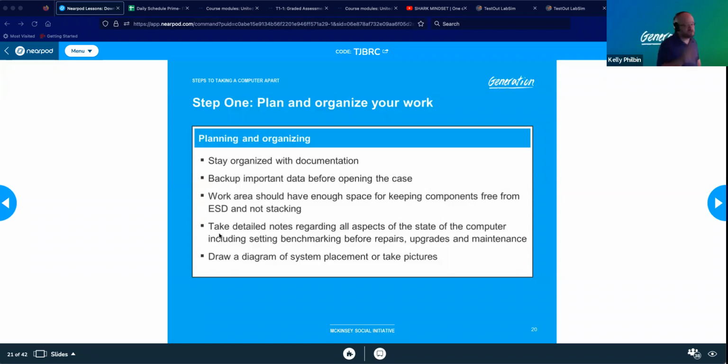The other thing is, if you're removing screws from a computer, this is not as important on desktops. They tend to use the same threadings and size, but on all laptops, mobile devices, phones, all that stuff, they have a nasty habit of each individual screw being a different thread and size. And if you put a long screw into a short threaded screw area, you could crack the screen on a phone. You could basically crack a chip or damage a chip, something like that. So you have to essentially create a map for yourself of where the screws go.